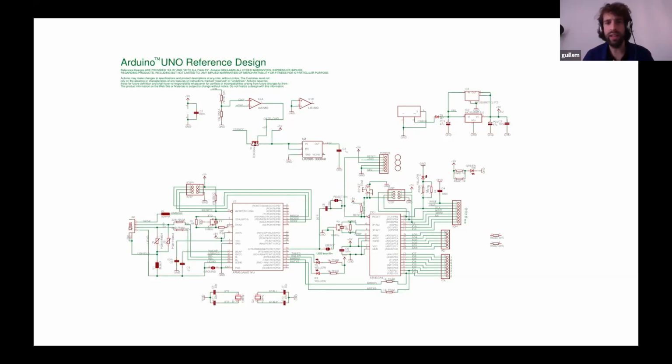And this is what the ESP32 you have does. It usually has a built-in serial to USB bridge, either an FTDI cable outside or a built-in integrated circuit on the PCB. So you are giving the possibility to the ESP32 to be programmed not just through a specific programmer, but through USB, which is a standard interface in our laptops. If our laptops talked serial like they used to in the 1990s, we wouldn't be using this. We might connect the ESP directly to our computers using a standard serial connector, but nowadays we need those.